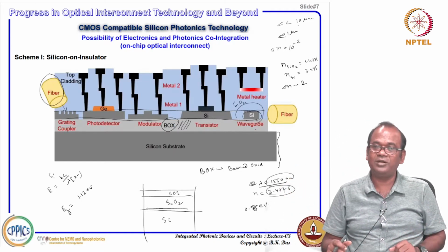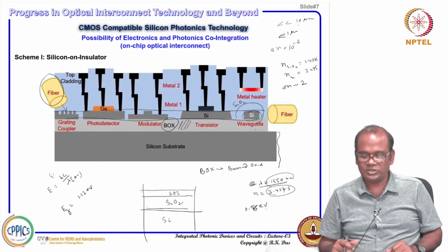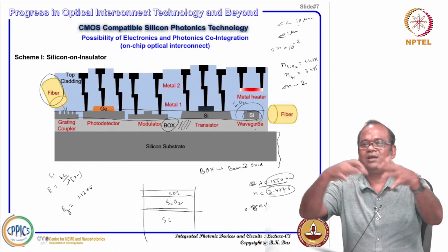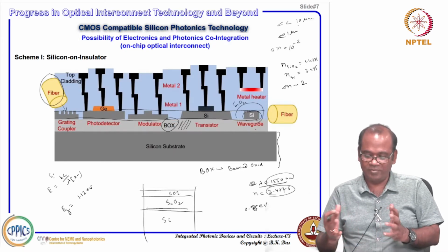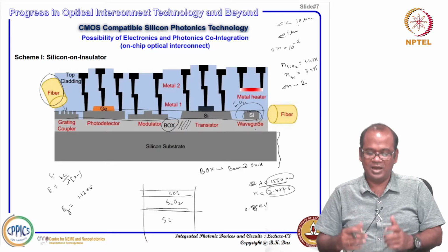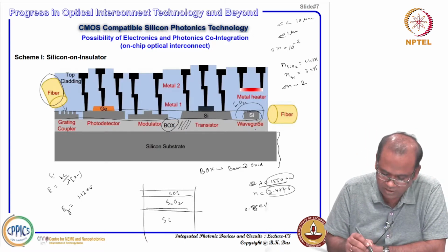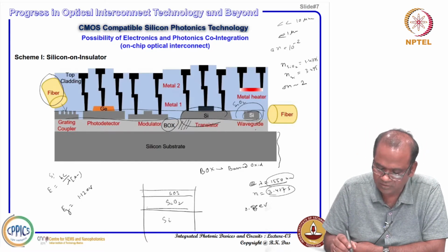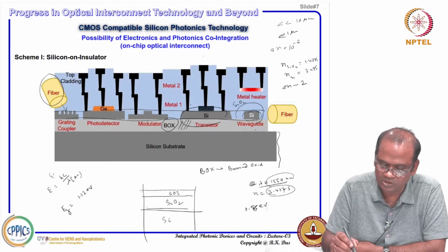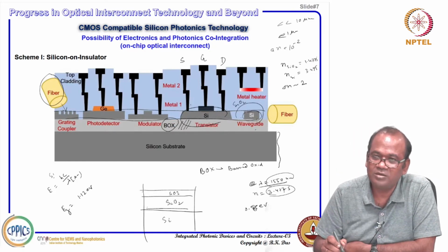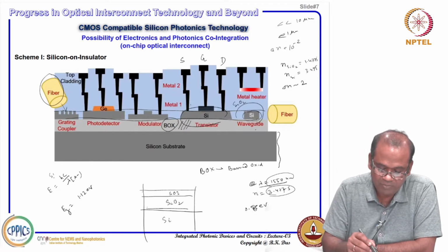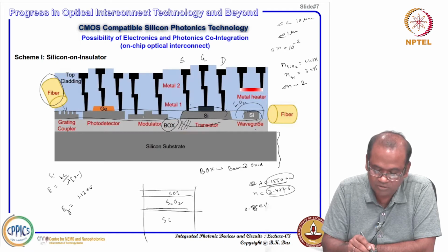Around 1550 nanometer, that wavelength is transparent in silicon, and the native oxide can act as a cladding, so that you get total internal reflection. So, the waveguide can be fabricated, and in the same layer you can fabricate a transistor in silicon, with p type doping, n type doping, this is your gate, this is source, this is drain, and you can use via metals. So, you can fabricate the waveguide, and this type of structure also.